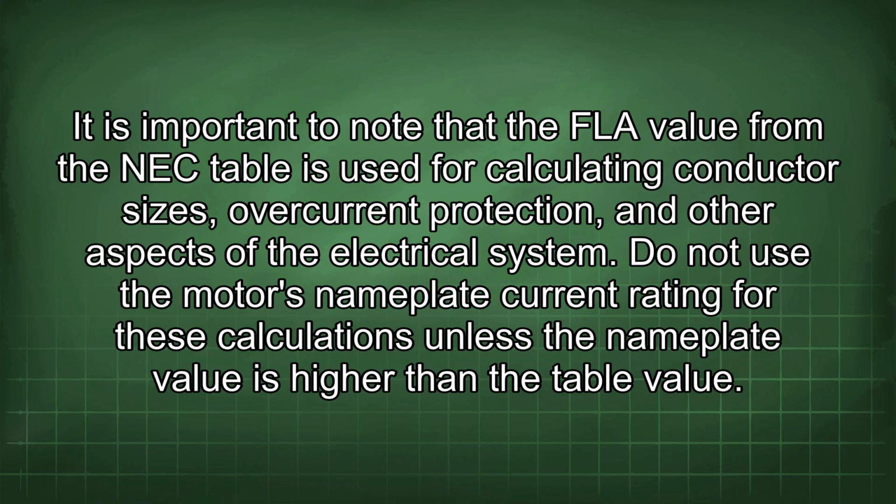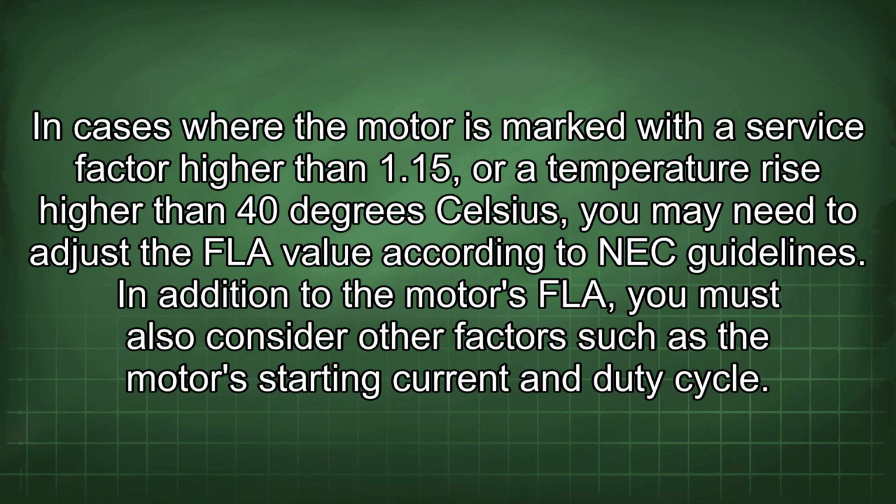Do not use the motor's nameplate current rating for these calculations unless the nameplate value is higher than the table value. In cases where the motor is marked with a service factor higher than 1.15 or a temperature rise higher than 40 degrees Celsius, you may need to adjust the FLA value according to NEC guidelines.